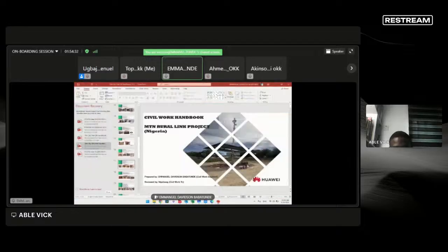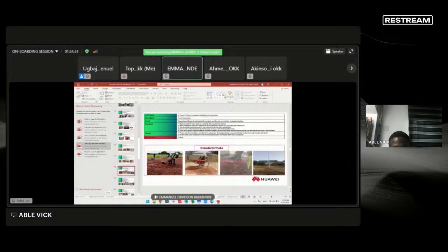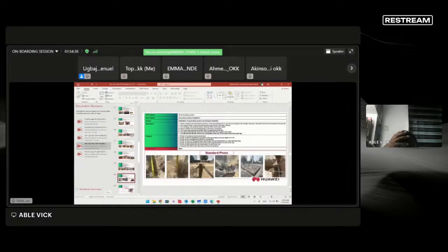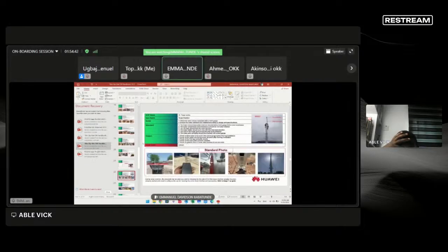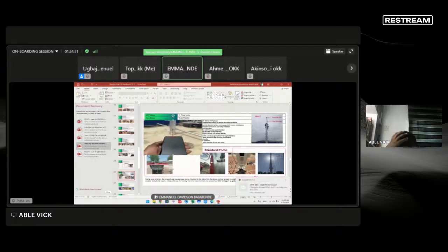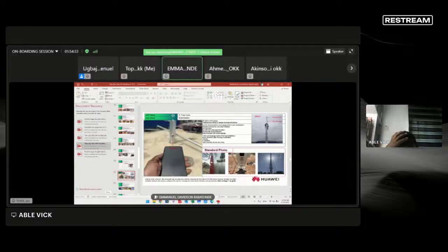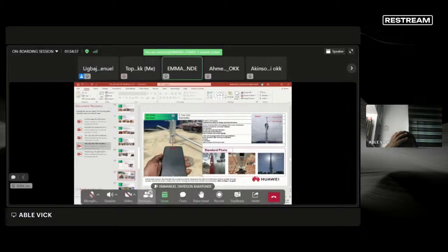So for a tower erection, before installing the first leg, you need to confirm the base plate level, just like this first picture. Then there's one hole that needs to face the south. You need to pay attention to it when installing. This hole has to face the south. Can you see this hole? In south.